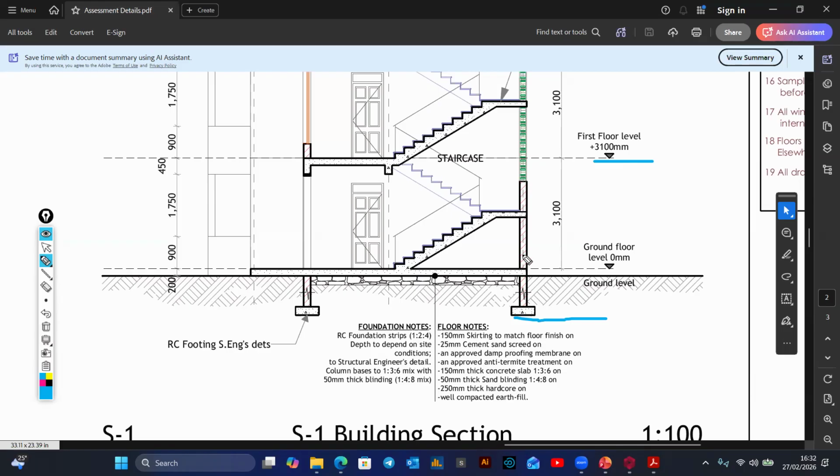Why is it like that? We do not design for this level, which is at the ground floor. This level is already strong. You're going to add the core, it's ground bearing. So when we are designing slabs, we start with suspended floors. Now, let us create this floor here, because that is what is going to happen in normal practice.